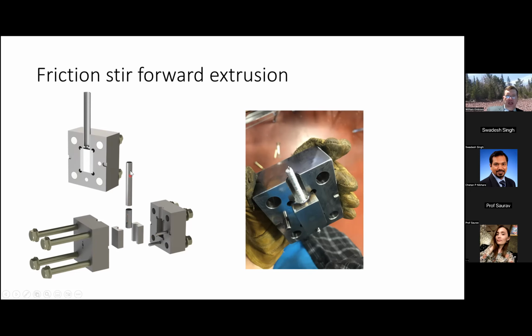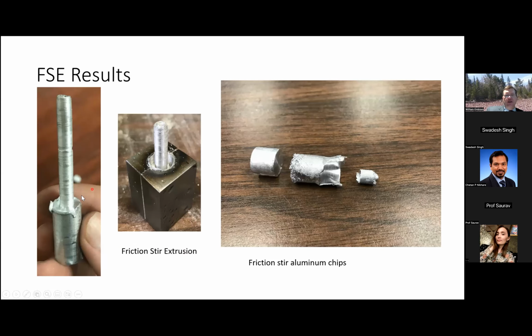And so here's our workpiece. Here's our hollow rotating probe, with the cross section shown here. And here's what happens with the workpiece still mounted within the die, having extruded out about 6 millimeters, and our initial diameter is about 12.5 millimeters. Here's another picture of the extruded parts sticking out of the workpiece. And this extrusion was actually within the rotating probe, which was hollow.